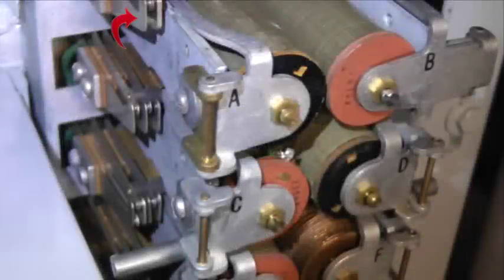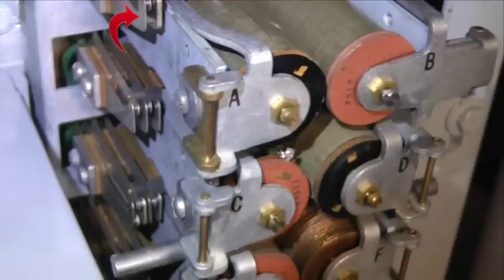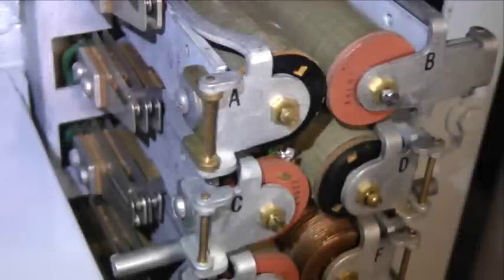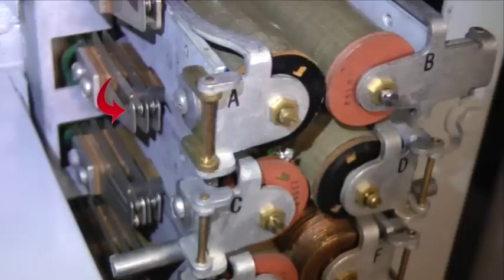At the end of the tens digit pulsing, the loop closes and the A relay reoperates. The vertical armature releases and its pawl disengages from the vertical ratchet. With the A relay remaining operated for an extended period, the holding path for the slow release C relay is opened for sufficient time to permit its release. It remains released for the duration of the call.